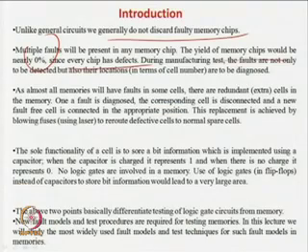So in all memories we find some cells that are actually redundant, some extra cells are there in the memory, because you have to repair and sell. If you are saying that you are shipping a 1 GB memory, you cannot give 512 MB kind of a thing, that is not possible. So you have to somehow fabricate more area than what you are claiming, and then you have to repair the chips. Somehow you have to do something with the faulty part of your IC, and then replace them with the redundant cells, so that totally 1 GB you are shipping. It is something like, say, you have to ship some 10 mangoes and 1 or 2 mangoes may be rotten.